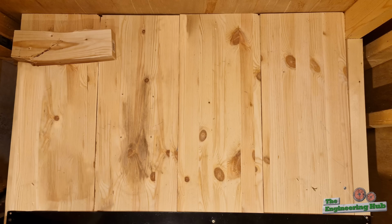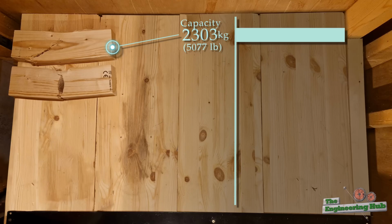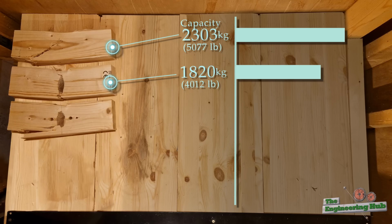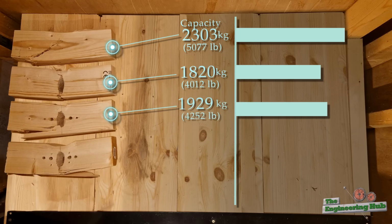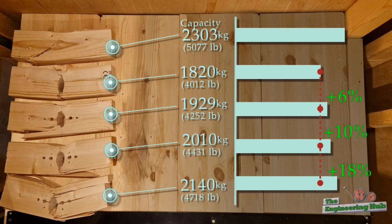In summary, the unaltered 2x4 achieved a load of 2300 kilos and failed in what appears to be a shear failure. The beam with a hole but without relief holes failed at 1820 kilos, while the beams with relief holes failed at 1930 kilos, 2010 kilos, and 2140 kilos. So, drilling relief holes provided a capacity increase of 6, 10, and 18%. Keep in mind that if holes are drilled at a wrong place, the structural integrity of the element can be severely hindered, so I do not recommend providing relief holes unless consulted with a professional.